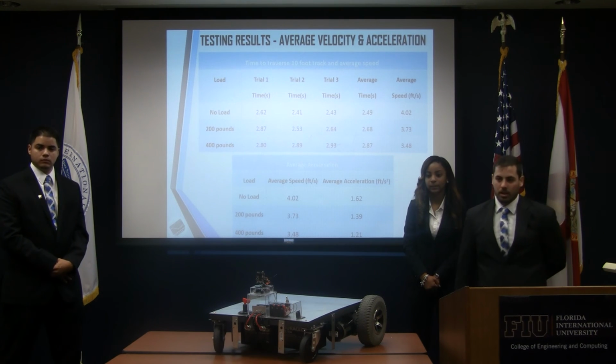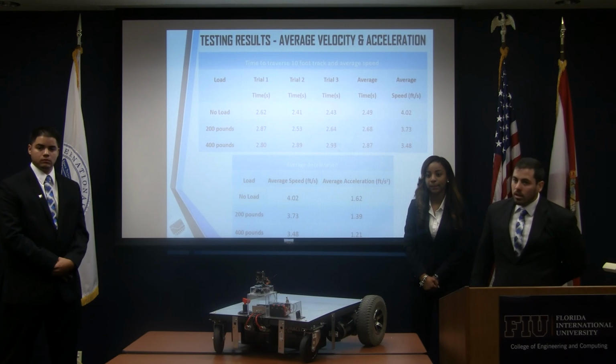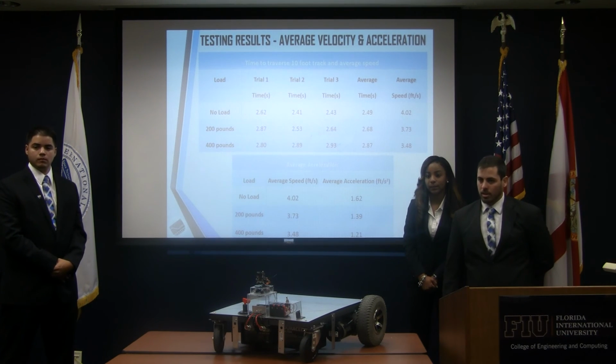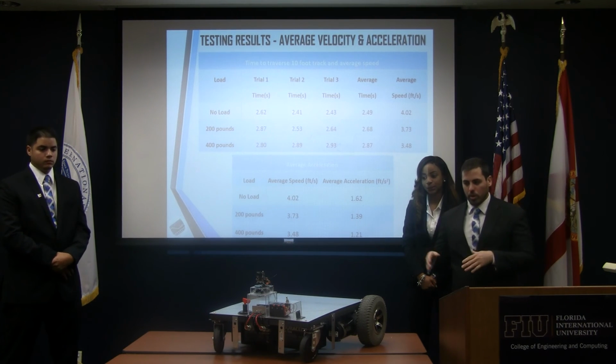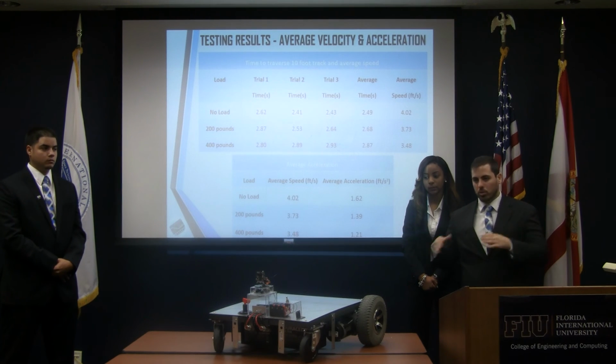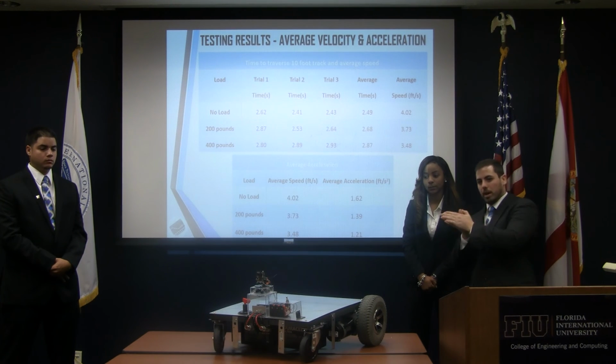Are there limits to the autonomous? In other words, I noticed the camera's not rotating, so you're not using the ability to look three-dimensionally around this device. No, so basically in the programming we have 180 degrees. If it can't pick up the target, the actual robot will stop and the camera will sweep back and forth, go up, sweep, back and forth until it finds the target.